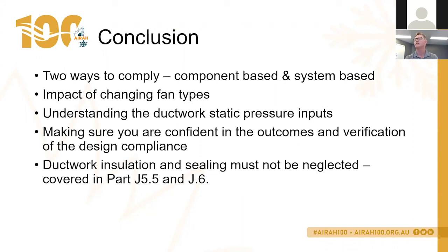The calculator just lists a coil, and it'd be the pressure drop across the coil based on the number of rows of the coil. So a DX coil will have a number of rows and a pressure drop across the coil. So you just use a coil, as far as I understand how the calculator works.